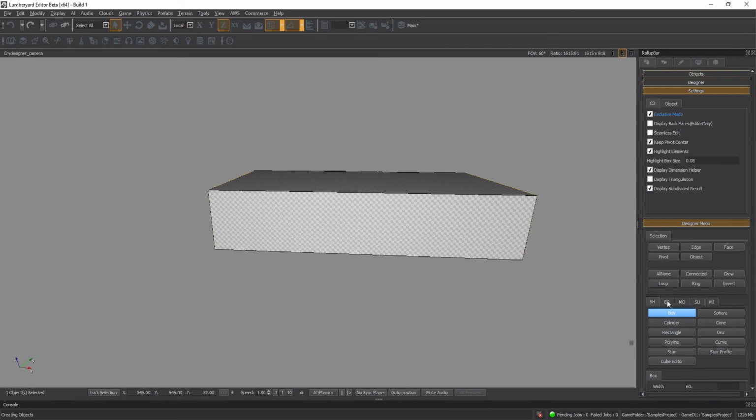One of the first tools I would like to cover is the loop cut tool. This is your baby. This is your jam. Anytime you need to insert an edge loop, go ahead and select this. So you can see we have the purple indicator here. One thing I would like to point out is anytime you are setting your first loop cut on an object, it always splits the object exactly in the center. So that is very, very useful for creating symmetrical shapes.